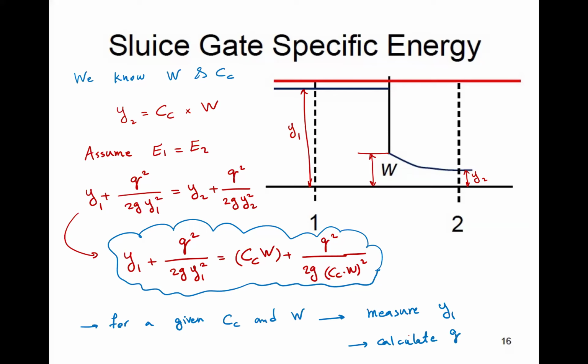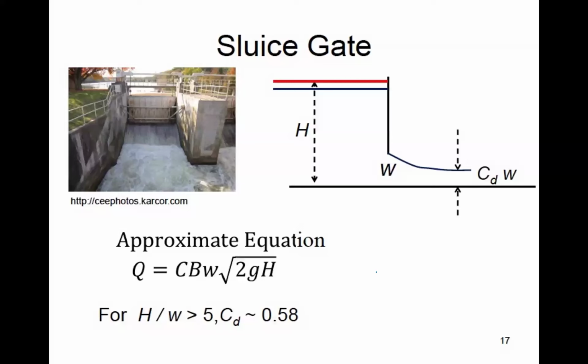So this ended up being another hydraulic control, because there's a direct relationship between depth upstream and discharge. If you recall, when we were looking at water surface profiles, in some cases we had a gate and we said we start from the gate because it's a hydraulic control. We didn't know why, but this should clarify that. So in practice,